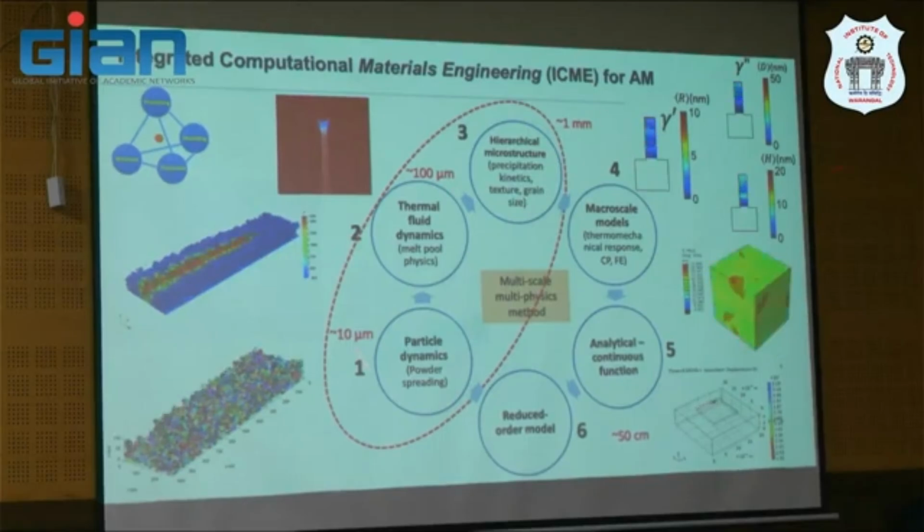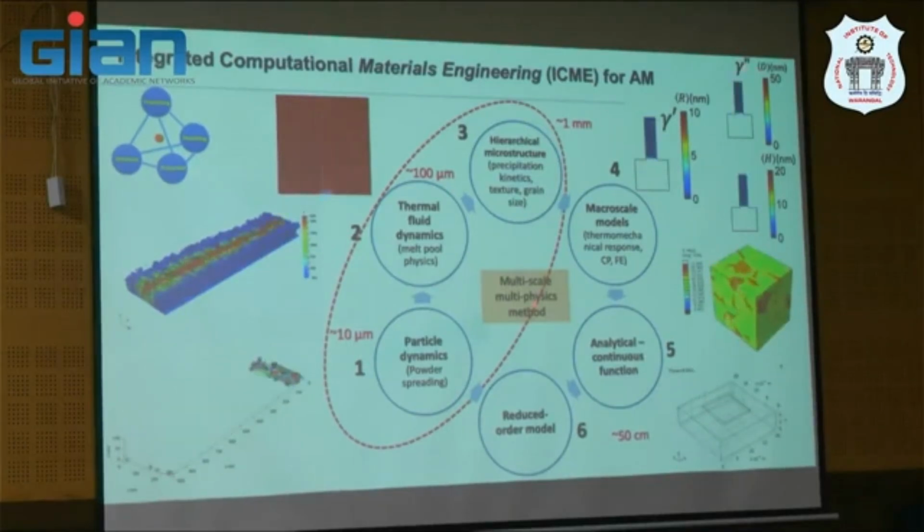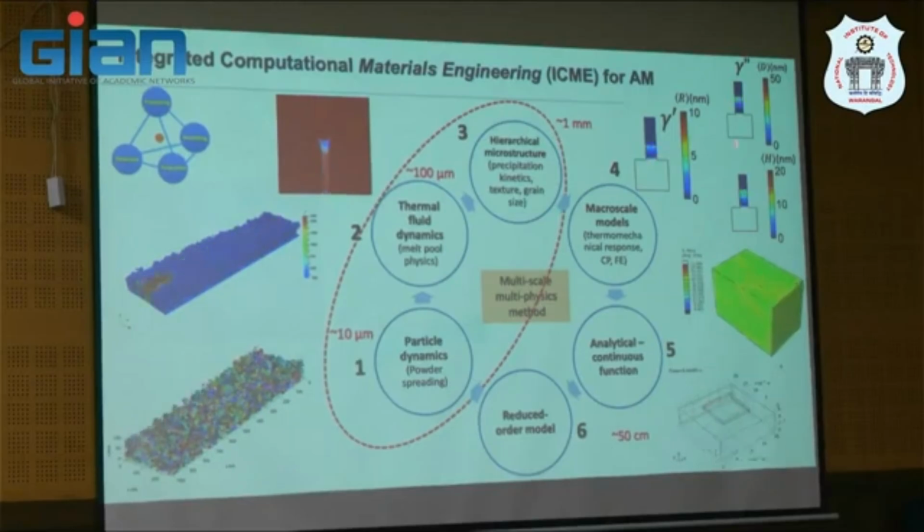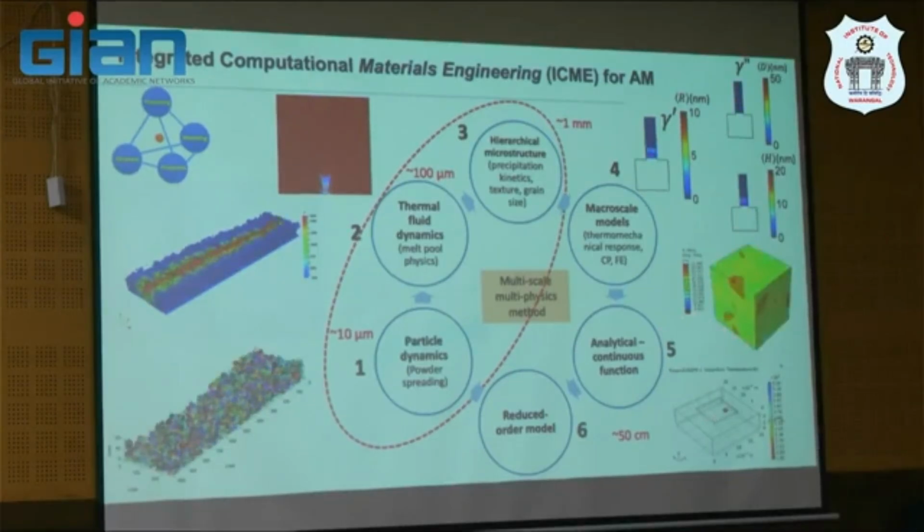Before that, if you use Inconel 718 here, you may need to predict the gamma prime, gamma double prime, and delta distribution along the build direction, which is quite surprising, as you will see the wavelength is not uniform anymore. And this information should be inserted into the mechanical model to predict the correct property induced by the signature of the process.